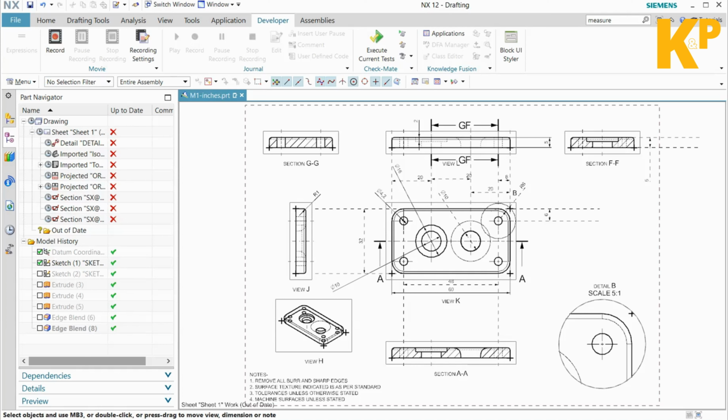Or let's simplify it. Let's talk about adding dimensions into your drawing. And how do you add dimensions? To add those dimensions you use references. You use either the edge reference, the point reference, the center line of a circle, or an edge like this, or a line, a drafting line like this.